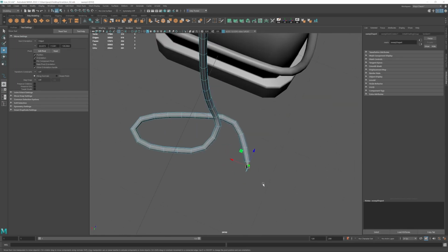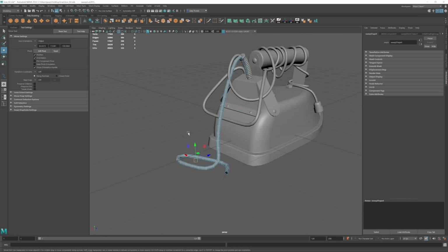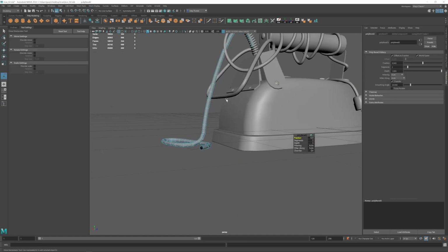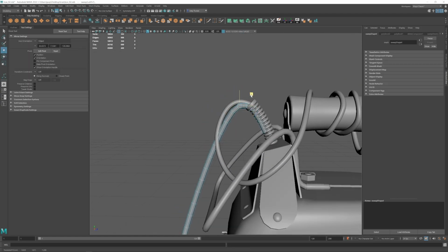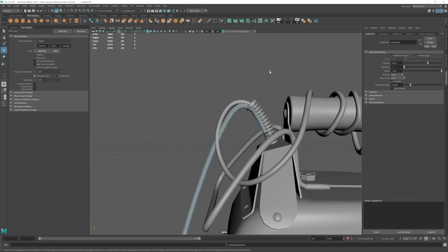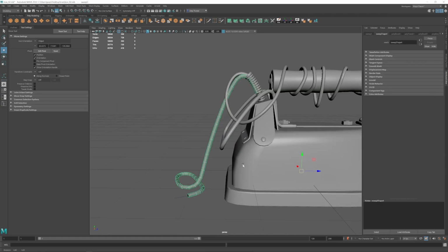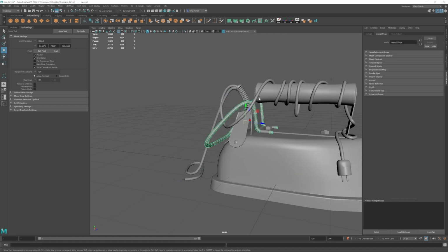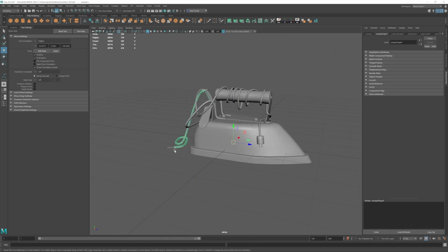So if I was going to do something this small, I would just make some little small bevels in some of these harsh corners, especially if you're going to be up close, and even that may not be necessary. You can make it really, really low if you really wanted. And as you can see, that small little chord we just created is around 700 polys, whereas the other one's upwards of 13,000 polys. So making these small little changes can go a long way.